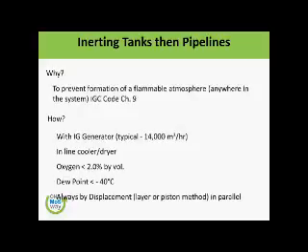But we are saying always by displacement, because displacement takes lesser time. Dilution takes very long time. Dilution is also a method, but dilution is never a really good process. So it is a layer or piston method in parallel. Technically the heavier gas pushes off the lighter gas from the ventilation lines, and of course that will change the whole environment. It is exactly like feeling liquid in your tank and taking out the gases inside.